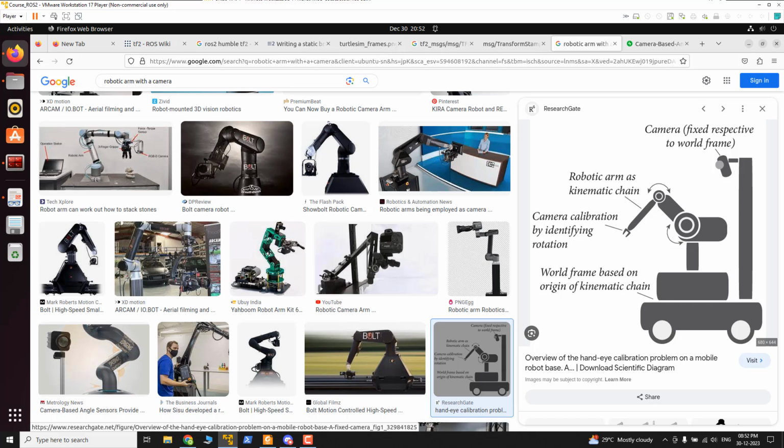There is a transformation between, obviously, the camera will get the object coordinate, and then after that we have to transform the camera coordinates into the end effector, okay. So basically we are multiplying the transformation to the end effector pose, and you will get the pose of the object with respect to the gripper or with respect to the end effector. So the static TF is mainly used for that kind of application.